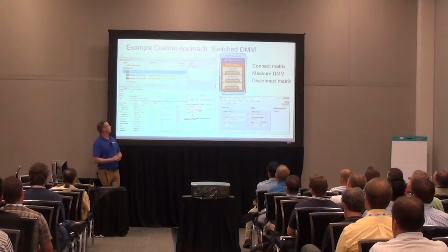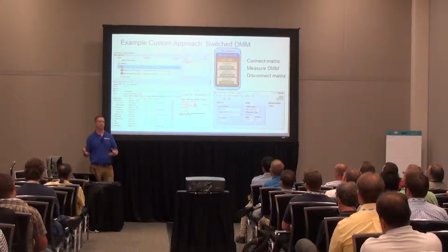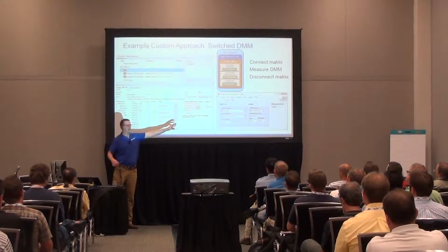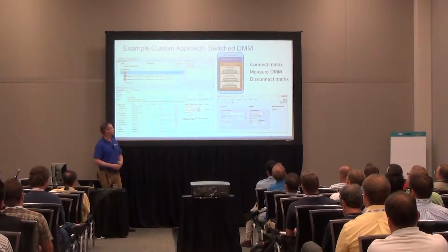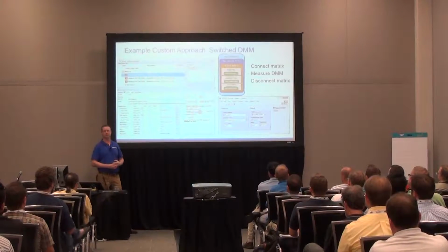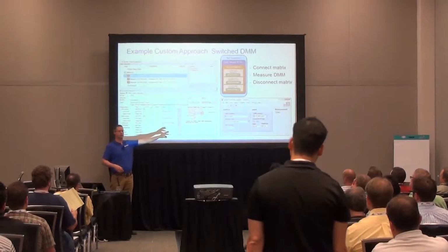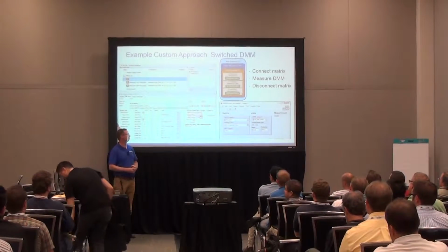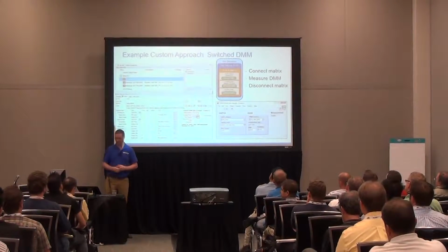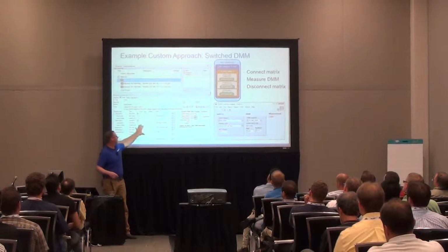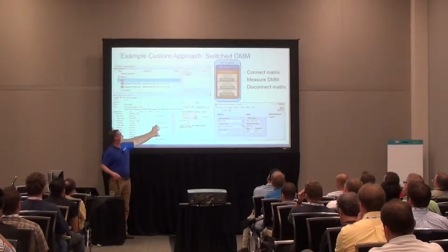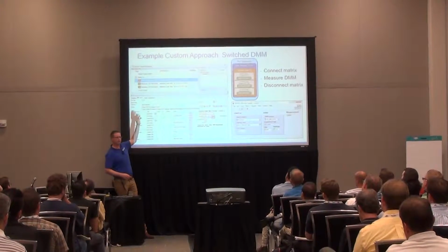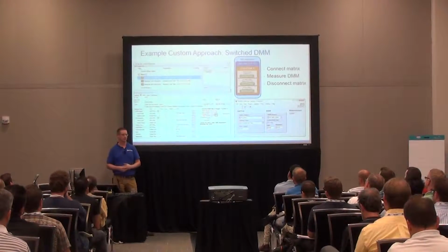As an example, let's take a switch to DMM, which is one of the most common things we would do in a piece of automated test equipment. Here on the right, you have almost exactly what is in the NI Example Finder for a switch to DMM example. You define your switch resource and what the topology is. In this case, we're using a MUX, so you have to define what channel you're using for that MUX. Then you do the same thing with your DMM. In TestStand, you call that VI. You have all those inputs and outputs. You pass those in, and from your step definitions, you can see we might call this a dozen or 100 times within a test sequence.